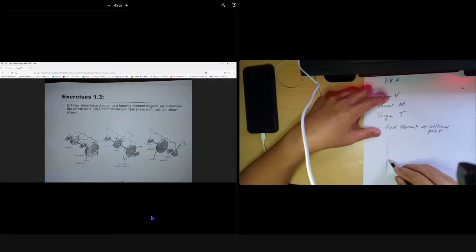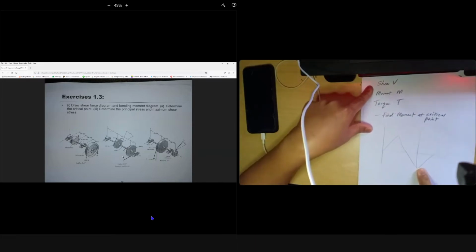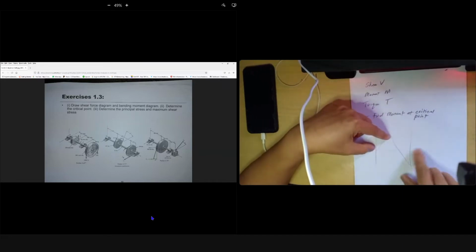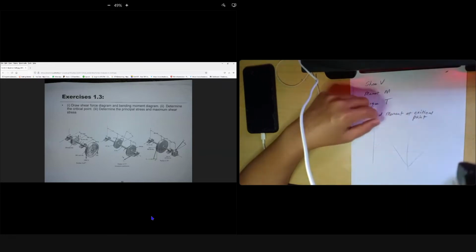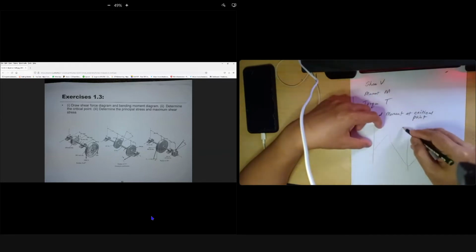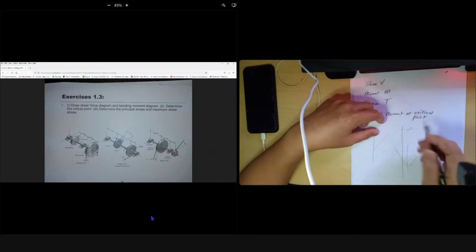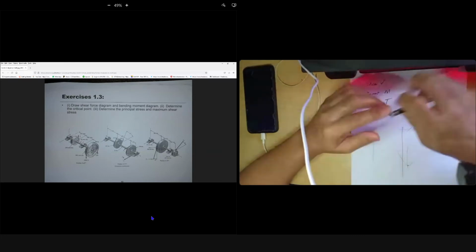If you look at your moment diagram, it could be like this, right? It could even be negative also. If the magnitude is much greater than the positive moment, then the negative side, in compression, is most critical. Understand? That is not your shoulder. The shoulder could be, you remember, 10 millimeter offset, right? Where is the shoulder, at your point, not at the peak moment? I hope you understand what I'm talking about. Do you understand or not?